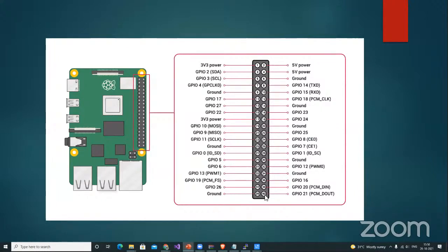Okay, I accept that. But these pin numbers are not equal to the actual general purpose input output. Here you can see for the 40th pin number, you can see GPIO 21. And for GPIO 14, the pin number allocated is 8. If you need to use the actual board numbers, you can go ahead, but it is always recommended to use the BCM numberings. For that only we are setting the mode to choose everything according to the BCM numbers.